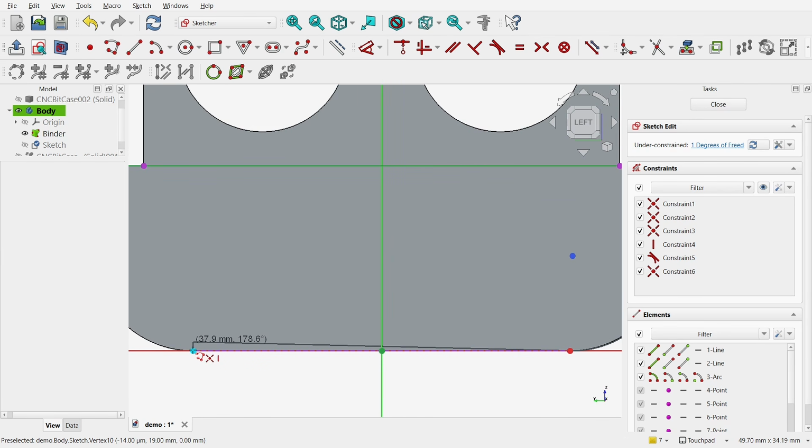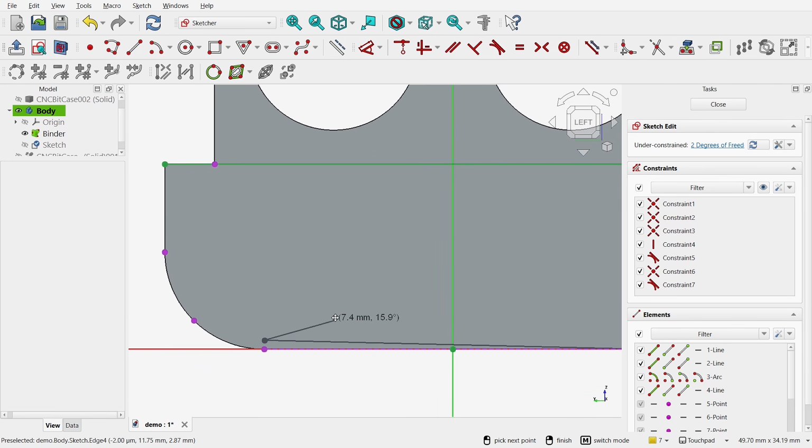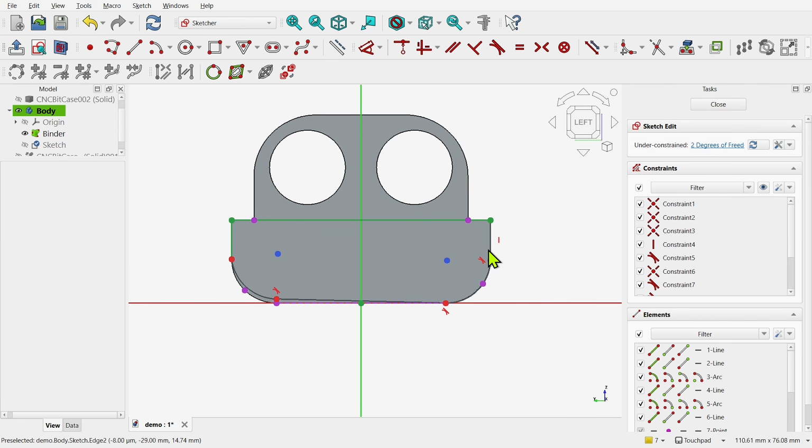Let's come over to this point, connect. And, well, I've missed that point. We'll sort that out in a moment. Come up to the top, again, hover over it, press the M key to create the arc, and connect up. And finally, press the M key to get the right connection to here, closing the polyline. So you see, after a right click, we have this geometry in here.